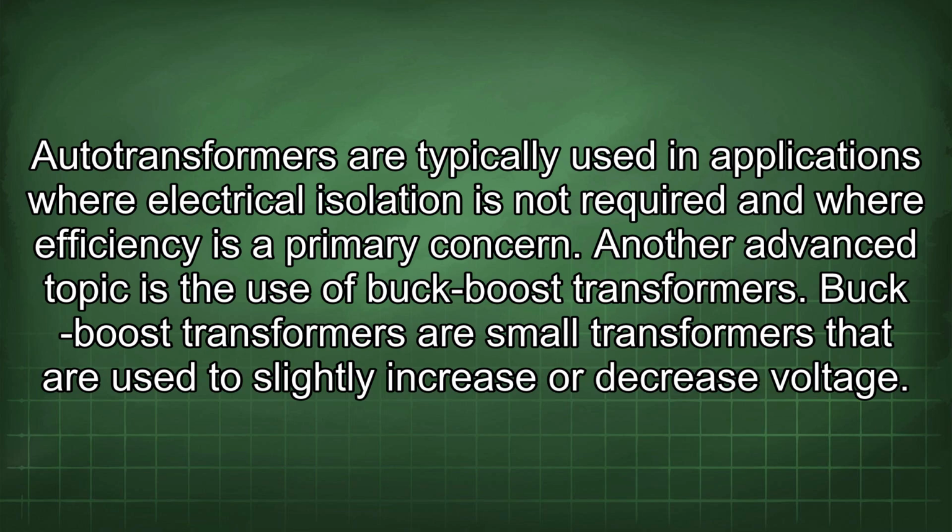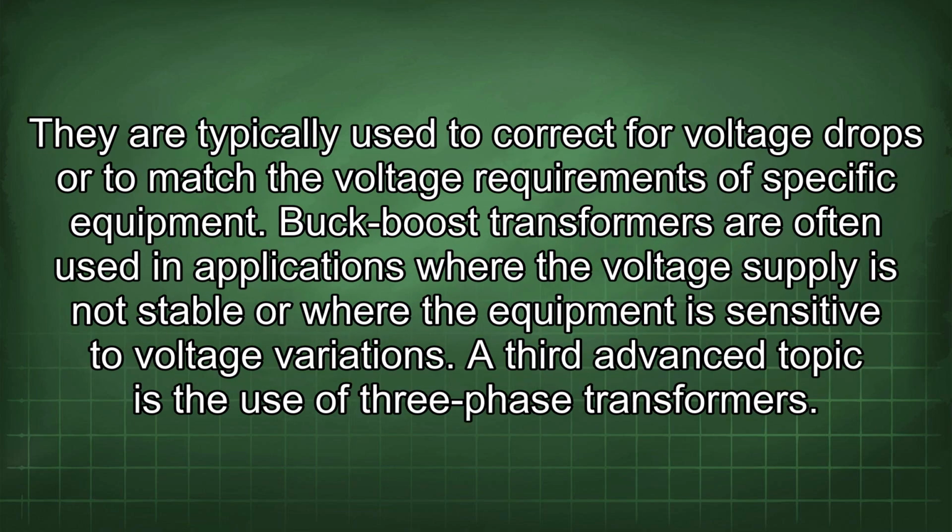Another advanced topic is the use of buck-boost transformers. Buck-boost transformers are small transformers that are used to slightly increase or decrease voltage. They are typically used to correct for voltage drops or to match the voltage requirements of specific equipment. Buck-boost transformers are often used in applications where the voltage supply is not stable or where the equipment is sensitive to voltage variations.